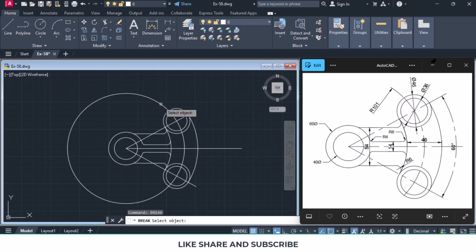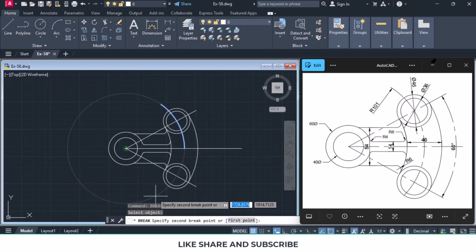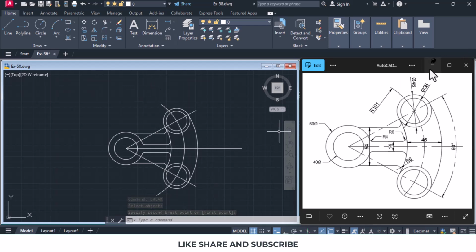Select the object to break is this, and specify up to where you want to break. Ensure that the whole circle is visible and then click break. So you get the broken arc like this. This is that extended broken arc.